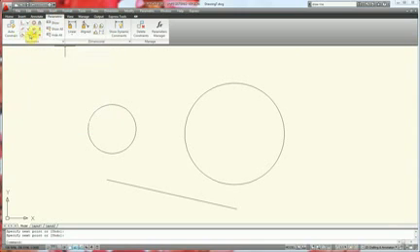And now that we're here, we have the geometric portion of this, which has our different geometric constraints. These constraints are such as the concentric constraint, a perpendicular constraint, coincident constraint. Basically what these do is they conform the geometry to these constraints. As well as we have the dimensional constraints that basically do the same thing. So we can give this size circle a certain diameter and it'll stick to that size. And we can also change these later, which you'll see, which makes design modifications really simple.